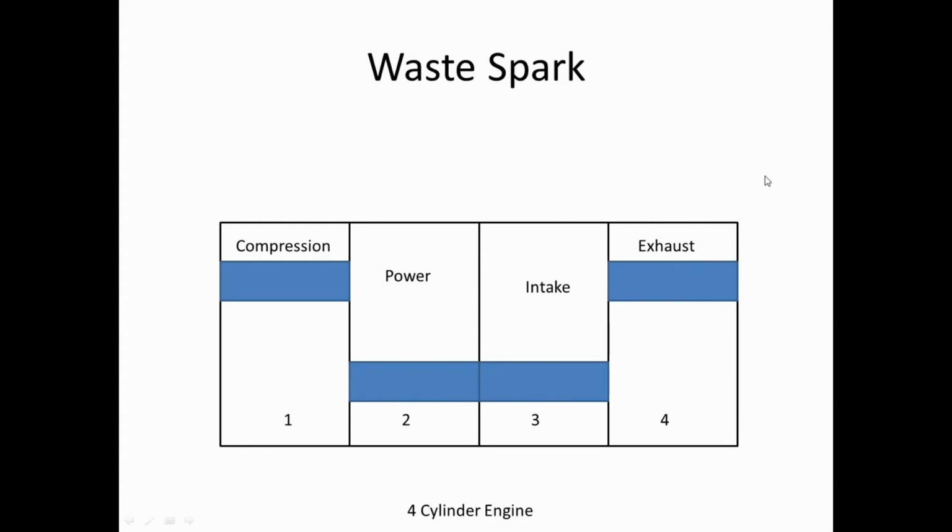It's the way the majority of four cylinders fire. I think my boat fires in a different order, but that's a two-stroke engine from the 60s or 70s, so that's a different ball game altogether, but the vast majority are 1, 3, 4, 2. So basically cylinder 1 is ready to fire.